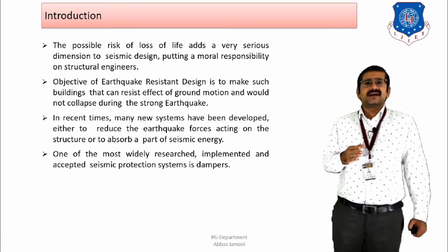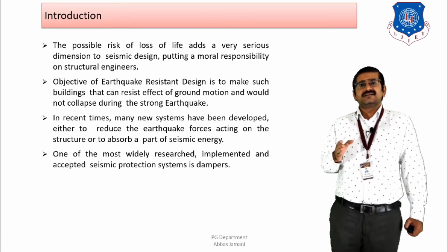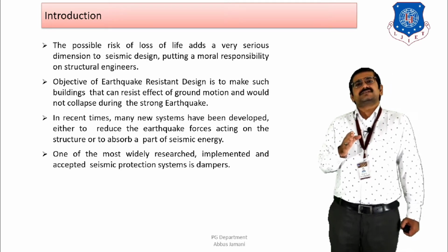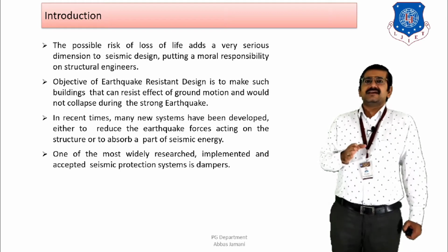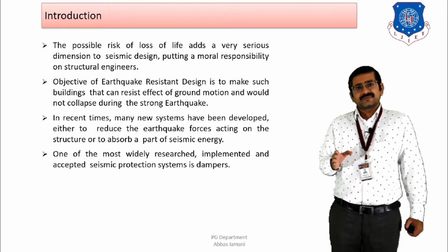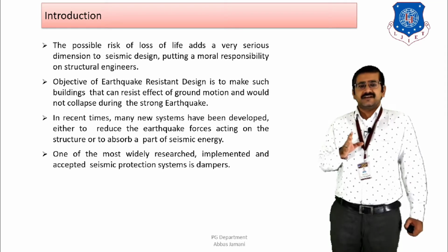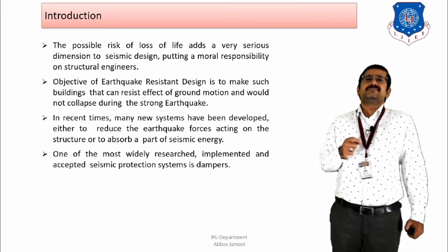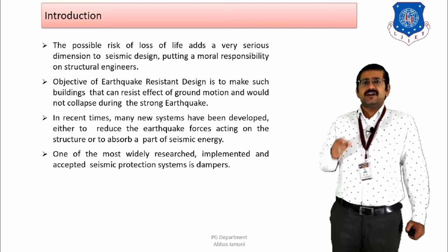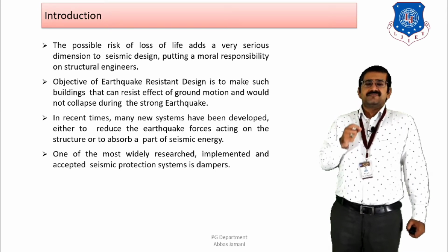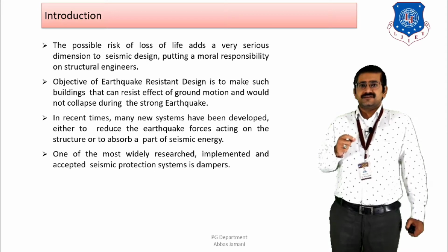In all three categories it is clearly mentioned that the structure is likely to undergo deformation, but collapse of the structure should not occur. In case of a strong earthquake, even if the damage is of irreparable nature and the structure is going to ultimately collapse, it should still give enough time for the people to evacuate and for the safety of the property.